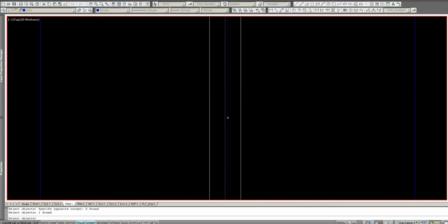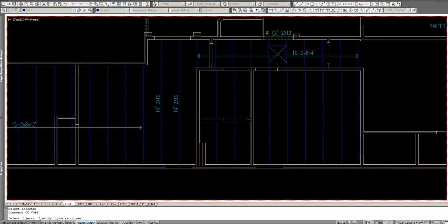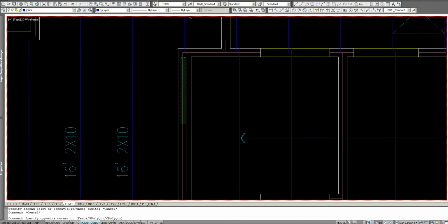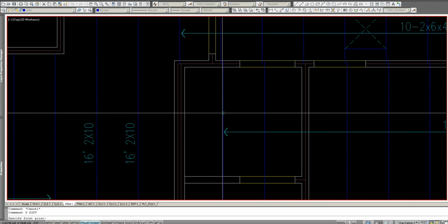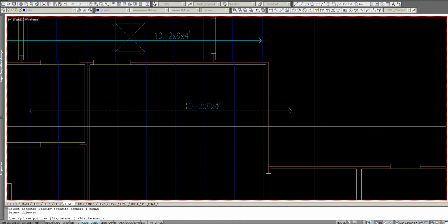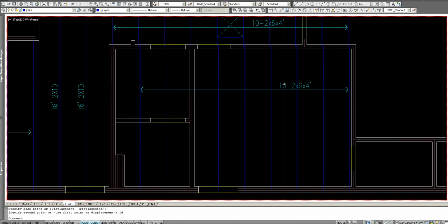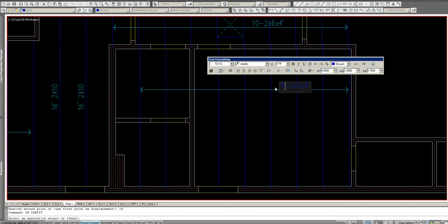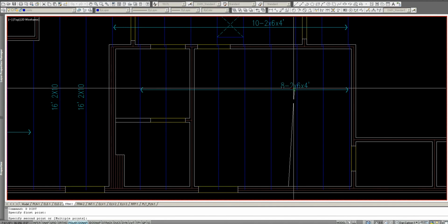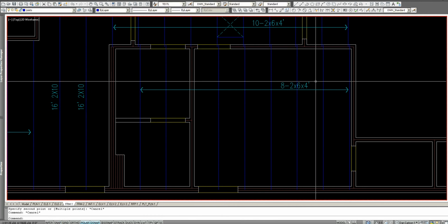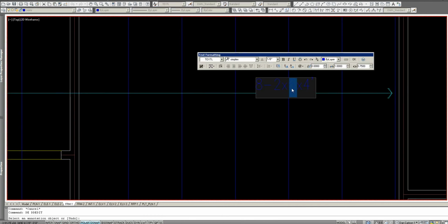We would not put a joist right over that wall. So let's copy this over here. Same thing here. There would be a joist here, but we don't need it. As long as that's 2 foot or less, we're fine, and it's 1 foot 10. So how many do we have? 1, 2, 3, 4, 5, 6, 7, 8. And this is actually a 10 foot 11 inch span, so it's 2 by 8. So we'll just do that. 2 by 8 by 12 foot.